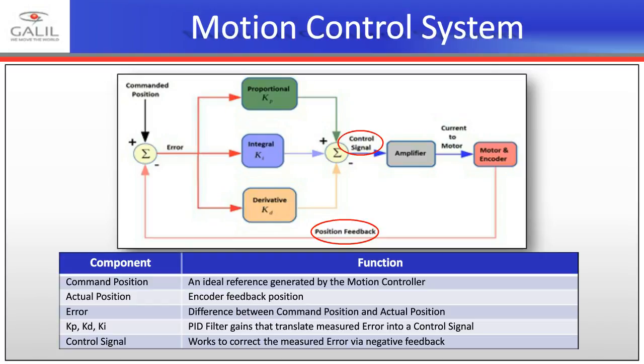Downsides: because every node on a network, so every amplifier, every controller, every I/O module, has to have its own microcontroller, essentially an onboard processing unit that can take that data coming out over Ethernet and pipe it to the hardware. And as mentioned before, this does introduce some latency, but depending on the system, this may be an issue or not.